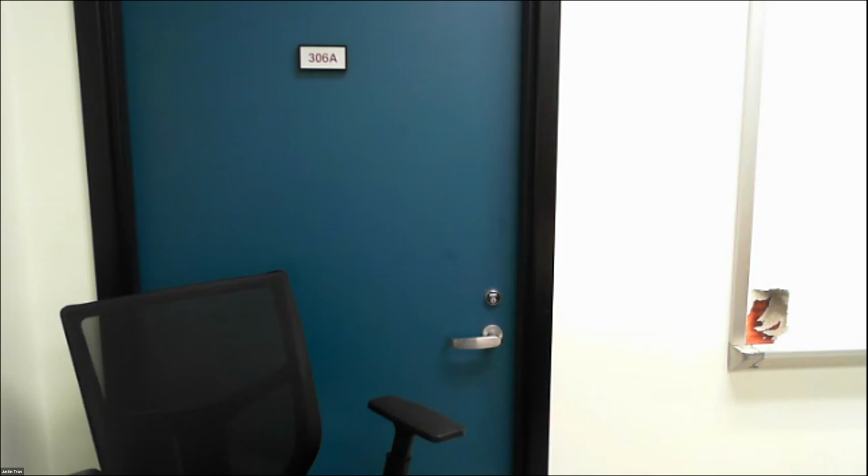So what you can do is delete that definition and make it again. Then in the bottom left details window, there will be a geometry field. You want to make sure that it says all geometries, or all bodies, and not just one.